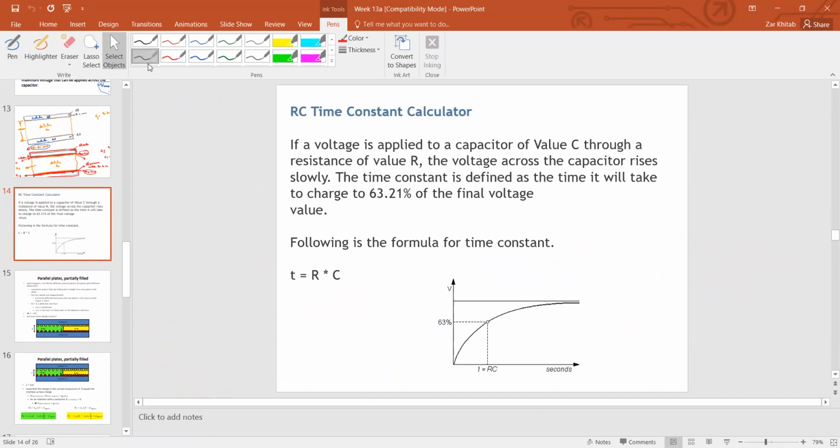And it affects the system performance, of course, because the capacitance will always bring the rise time for any circuit. The rise time is the rise in the voltage value. Because when you apply voltage to a certain device, the voltage will not suddenly rise to the maximum value. It will take a little time to rise to its maximum value. So the time taken by the voltage to rise to 63%, sometimes 66%, some other people quote 63% of its maximum value, is called the rise time.